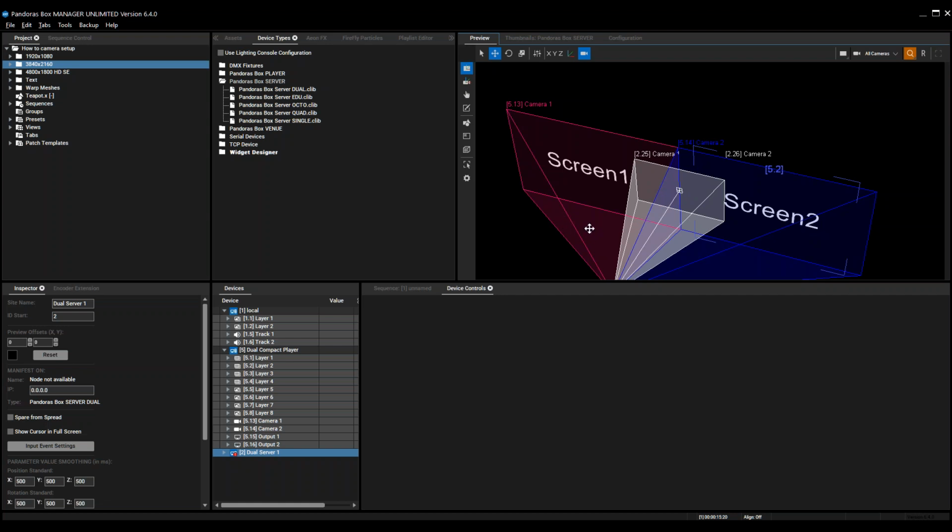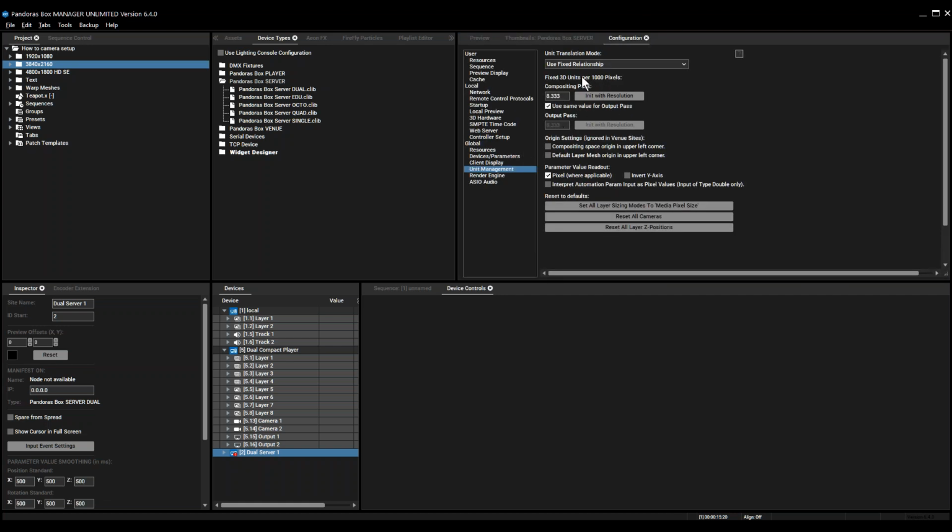So initialization is only once. So you have to work in one relation. And this is all what the unit management is doing. When you set your project up, you tell Pandoras Box what amount of pixels fit into 16 units, and that's all what the unit management is doing here. So either if I have those two possibilities, HD and UHD, I either set 16 units to UHD or I set it to HD. It's not changing the behavior, and it works in both ways.